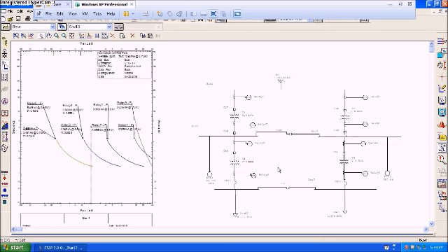Another concept can be explained by this. Suppose a power surge is there, then the relay need not trip unnecessarily, because it will affect the operation and efficiency. So we will provide a certain time lag after which the relay should operate. Suppose the power surge is there, then for a certain time the relay will not trip. So the power surge goes on and it will not affect the power system. So we can increase the efficiency and stop the unnecessary trippings.